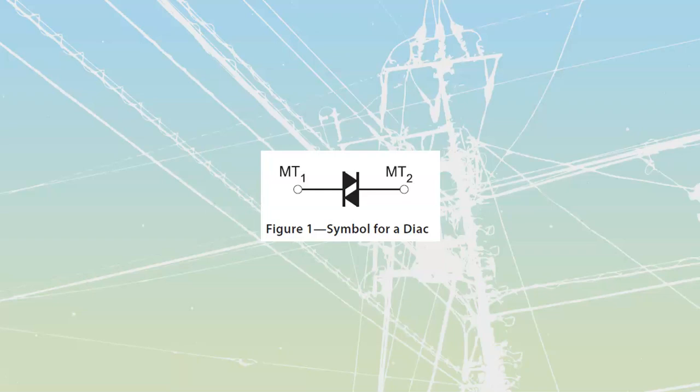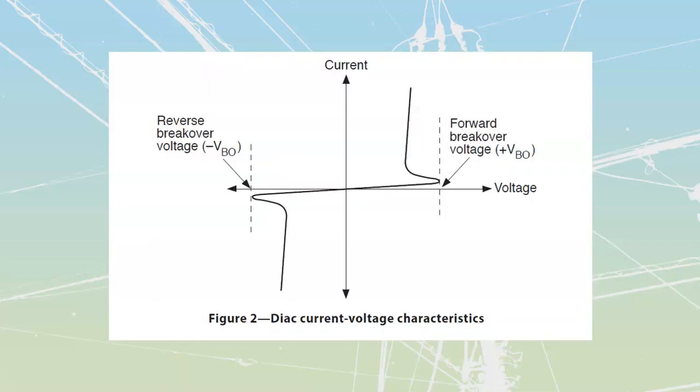What we'll use them for is as a breakover point that we can then use to trigger something else, because each of these is going to have a voltage rating. Whatever that voltage rating is, this thing can break over, go into conduction when it sees that across from terminal 1 to terminal 2. The voltage itself is going to be called the VBO, voltage breakover, that this thing will turn on with. And it gives us a graph that looks something like this.